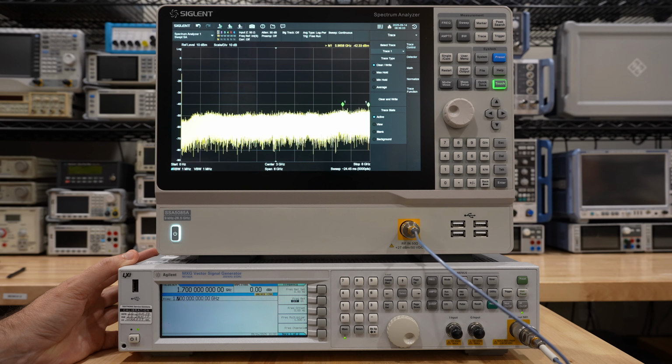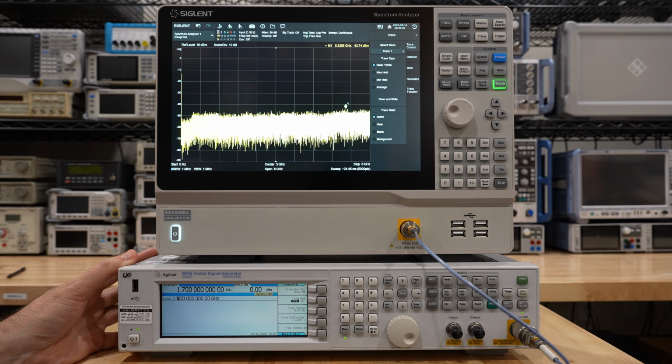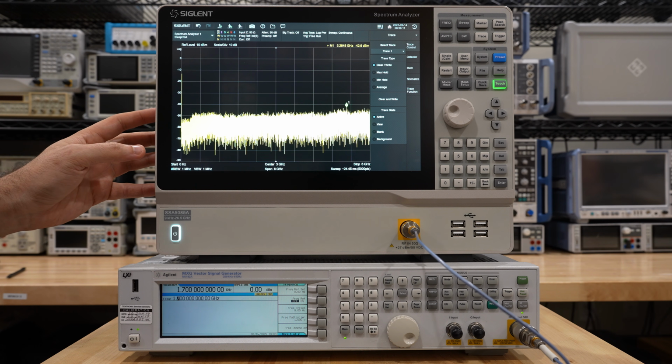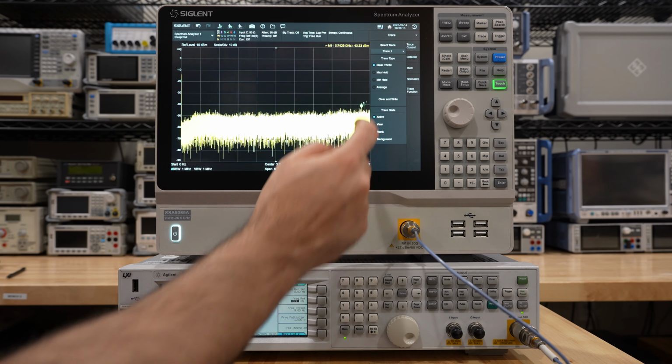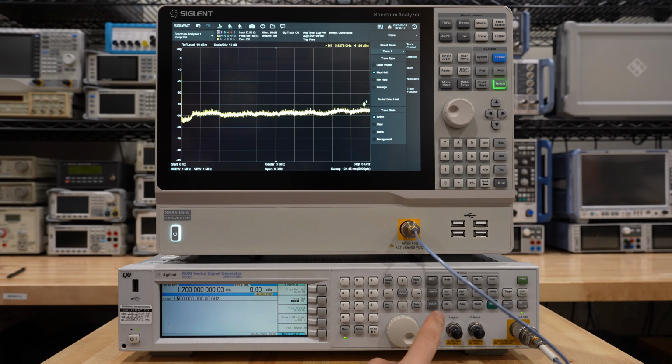Now, one thing we can do to get a good idea is to set a sweep on this. We can do a sweep across the entire frequency and then put this thing into continuous persistent mode so that it never clears up. For example, I can do a max hold. And then if I do a max hold over here, we can go over here. I've already set up the sweep, and I can turn the sweep on and let it go.